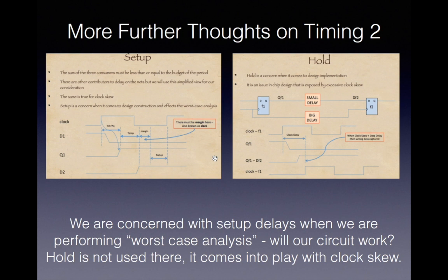Setup shows the period of time before the active edge of the clock. The data must be stable. Hold is the period of time after the active edge of the clock. The data must be stable.